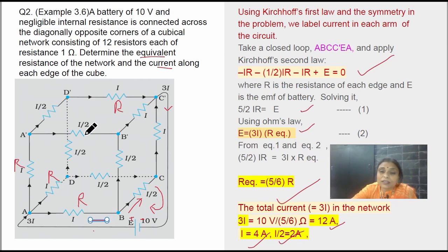So you can see using Kirchhoff's law, the circuit becomes very simple to solve. It's really easy, you just have to make the equations. If there is more than one value of current, make two equations, compare, and then simple mathematics gives you the required things. So I hope you will remember this. The loop law is the conservation of energy, and the junction law is the conservation of charge. Sigma I is equal to 0 is the first law. Sigma delta V is equal to 0 is the second law. I hope you have understood. Thank you.